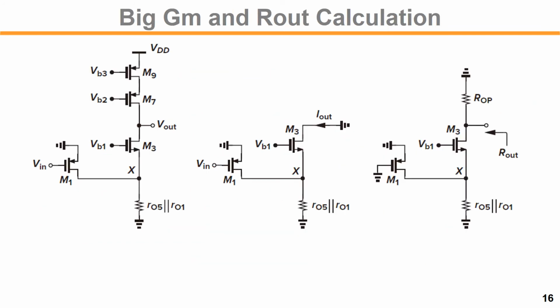The gain of the folded cascode amplifier can be easily derived by using this equivalent single-ended version of the amplifier. We have the common source. The source node is the AC ground. So our input goes to PMOS, and this will generate the current.